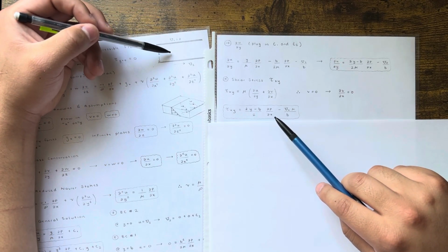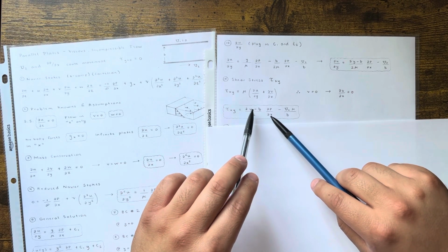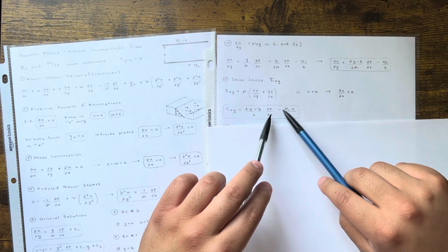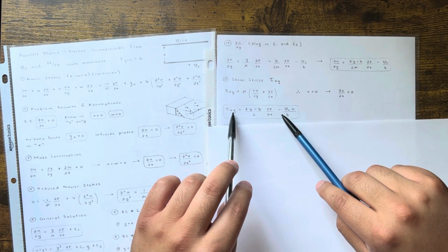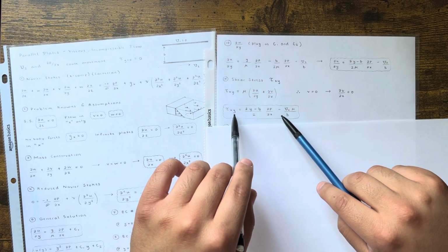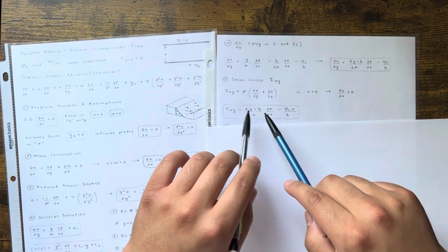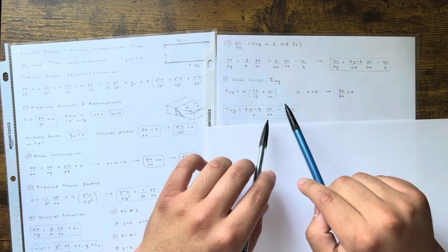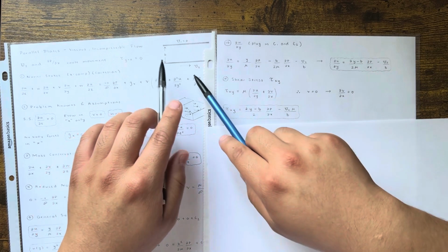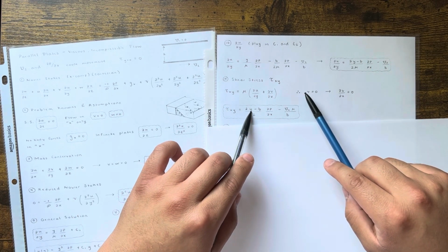If I wanted the shear stress right at the center, I'd plug in b over 2 for every y that I see, okay? Not the b, for every y. It's a function of y, okay? So for whatever shear stress I wanted, just plug in that value for y, and then just solve for it. In this case, I wanted it at y equals 0, okay? So when I plug in y is equal to 0, right?